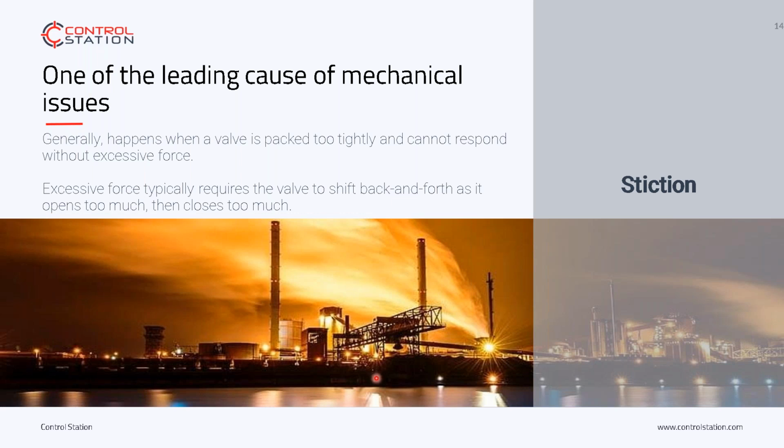Our expectation is perhaps too aggressive or too oscillatory, and it's causing the valve to move too far in one direction and move back and has to keep oscillating. It's over aggressive control. You may argue that we need fast response, but fast response is going to result in overuse of the valve, which will then ultimately lead to wear and tear.